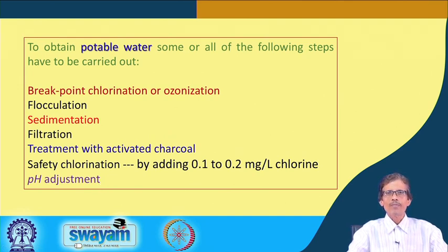If we find that the pH of that particular water is on the acidic side or the basic side, accordingly we have to go for acidification or addition of alkali, such as sodium hydroxide or potassium hydroxide, or sometimes a very dilute solution of ammonium hydroxide, which can change the acidity.